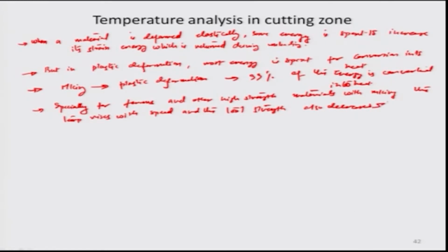So obviously it would create more tool wear, and sometimes even tool failure, okay, if the temperature is abnormally high. So this definitely should put a limit on the cutting speed, and that is why an analysis is needed of how much would be the optimum speed for all these different failure aspects to not creep in and have the machining operation carried out at a certain optimum speed.